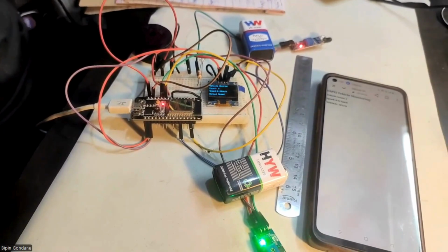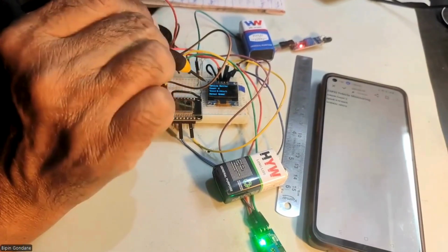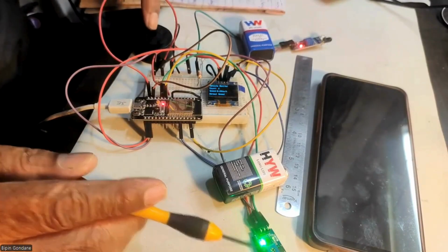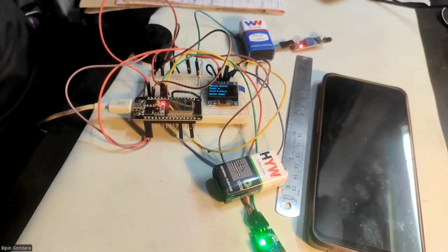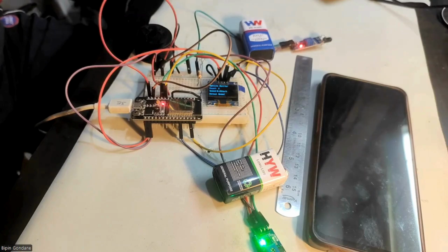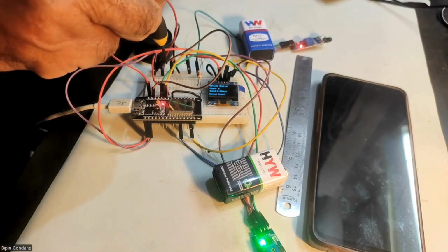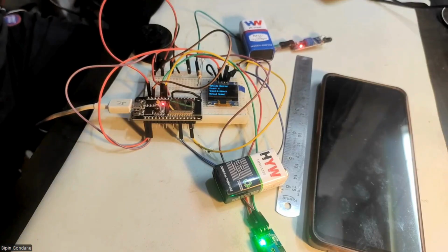So I will just tell you, very simple. OLED display, 2 IR sensors, 1 and 2, buzzer, LED. Already I have given you the idea of how it is connected. OLED is connected to pins 21 and 22, which are on this side. And the sensor pins are on this side. That is, these two sensor pins are from this side. Even the LED and buzzer are from this side.